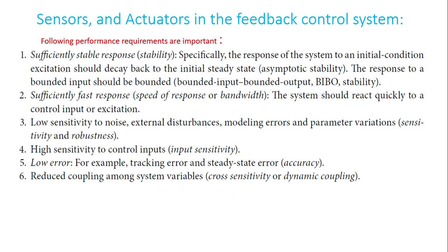Sensors, actuators in the feedback control system. The following performance requirements will be considered as important. The parameters which we are going to discuss regarding performance requirements are, first, a sufficiently stable response, that is stability. Specifically, the response of the system to an initial condition or excitation should decay to the steady state. The response will be bounded, that is bounded input bounded output, BIBO stability.